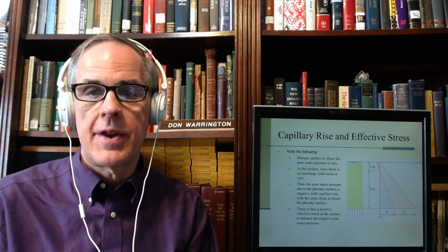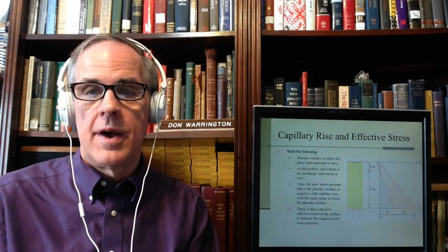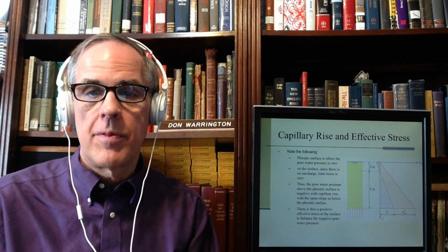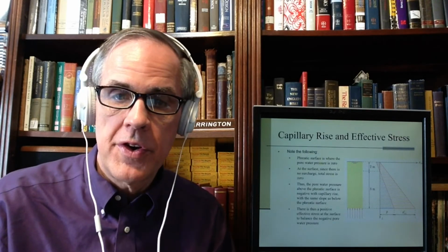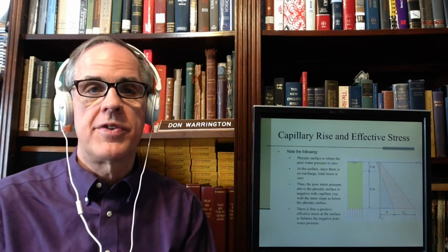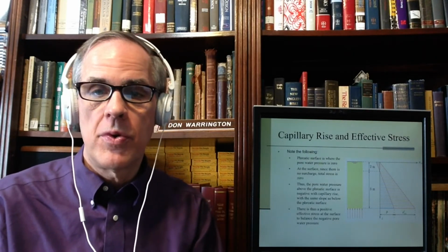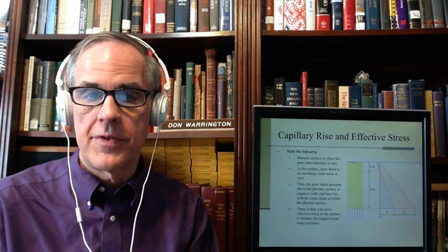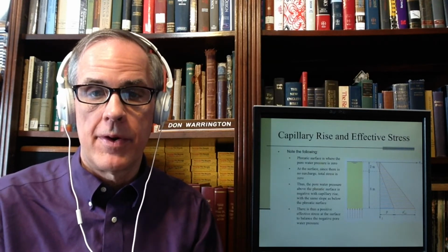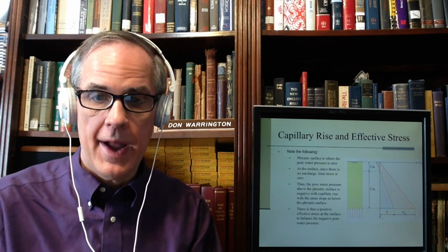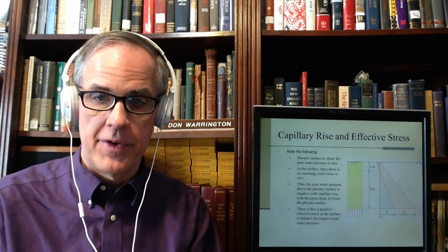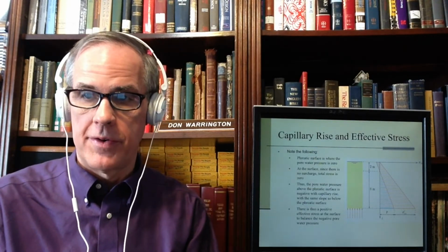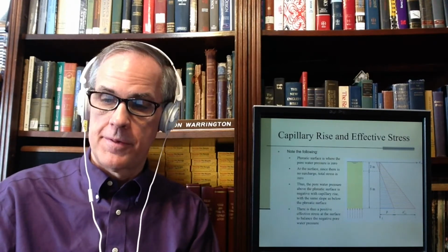Notice that the phreatic surface, again, is where the pore water pressure is 0. Since there is no surcharge, the total stress is 0. Thus, the pore water pressure above the phreatic surface is negative with capillary rise. And there's a positive effective stress at the surface to balance the negative pore water pressure. We're going to see this in calculations.